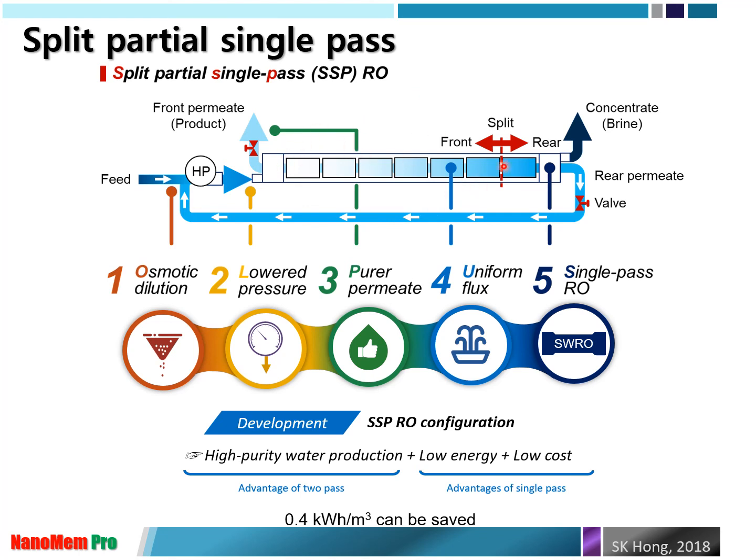That's the reason why you completely block the permeate at the end of the last modules and send it to the feed side, which will reduce the overall osmotic pressure, so energy can be reduced for low osmotic pressure, and your water quality can be improved.